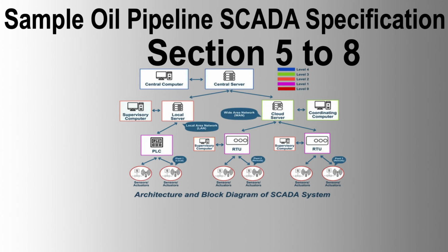5.6 RTU configuration. RTUs shall be self-contained units capable of collecting data from dry contacts, current or voltage signals, and contact-making pulsing devices. Features include no false outputs during power up or power down, a minimum of 256 unique RTU addresses. Selection interlock to prevent more than one control selection at a time. Remote downloading of configuration parameter changes and application software. Remote diagnostic capability. Programming tools for minor software modifications and configuration via handheld devices or IBM-compatible personal computers. Capability to modify the program offline and online while the system is operational.